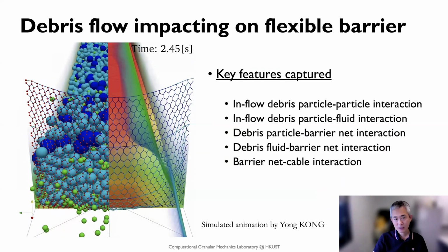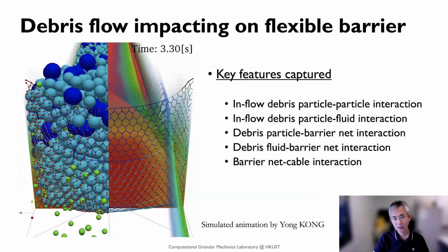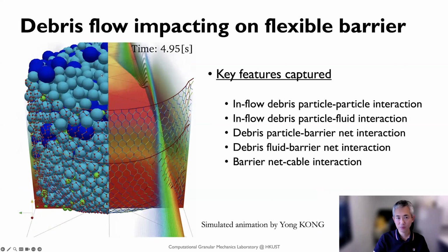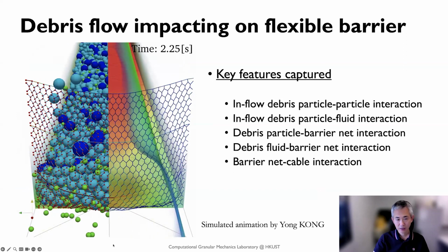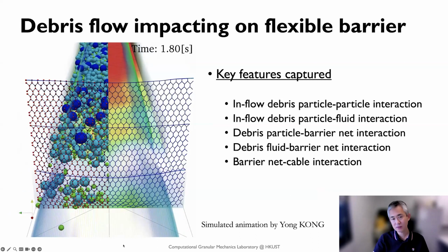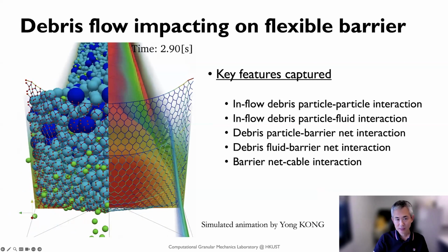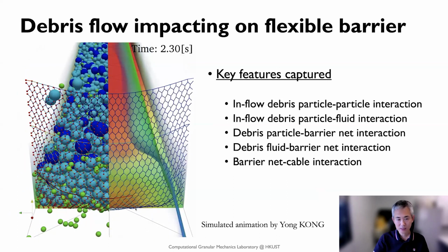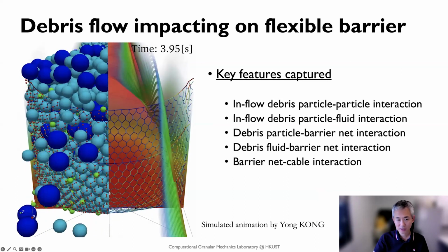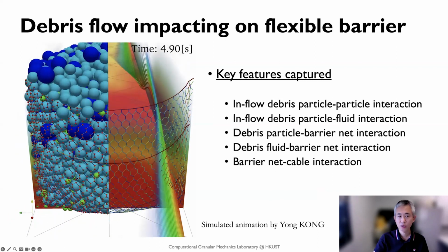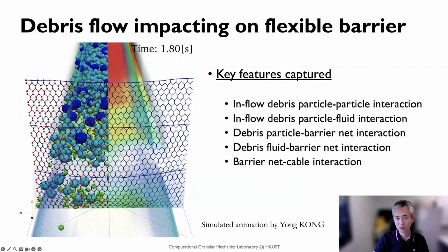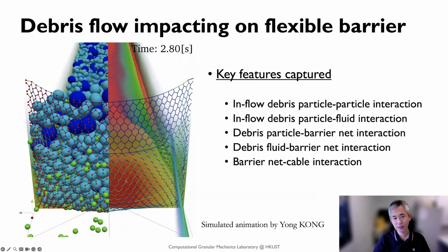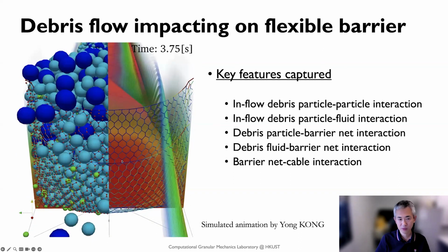We install such a twisted wire net, and then we subject it to a mixture of particles and fluid by CFD-DEM here. This is a typical simulation scenario that we can produce. We just split the visualization: on the left side, we only show the particle system, and on the right side, we only show the fluid streamlines. Actually, they are a mixture; that's for visualization purposes.